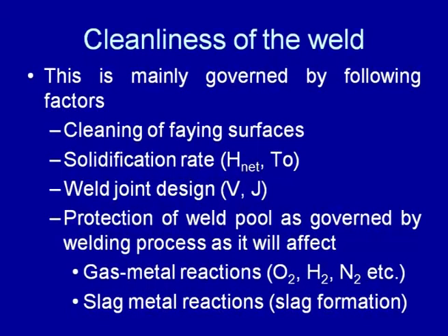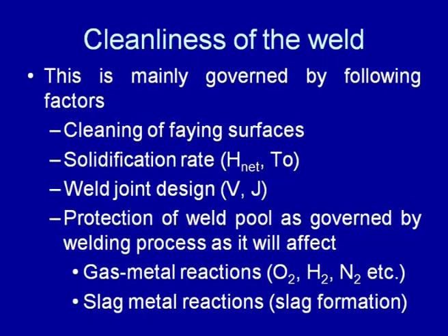And then the weld joint design: wide, meaning large groove angle V grooves offer better possibility for these impurities to come up to the surface and to produce a cleaner weld as compared to the U and J groove joint designs. So, the higher groove angle promotes the impurities to come up to the surface and produce a cleaner weld.